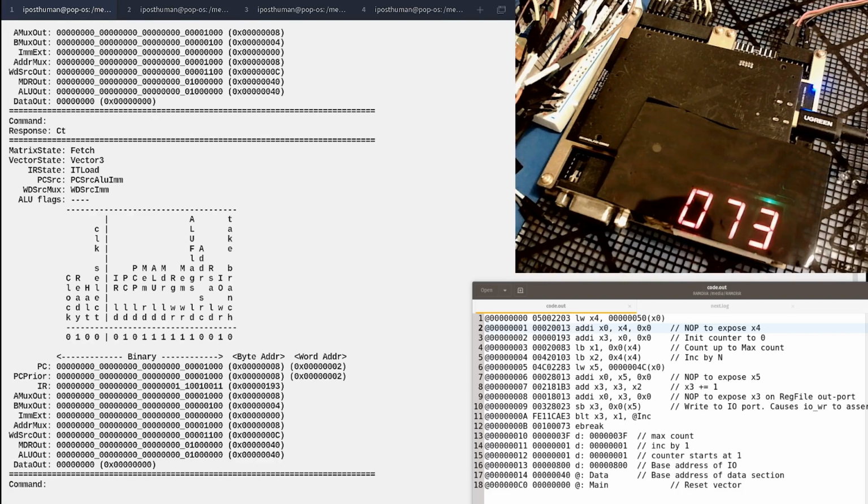There we are. We're now on the next instruction. This is a real instruction that we're actually adding to it. This particular one clears out the register. So we'll continue going through. It's fetching the next instruction. There it is, 2083. So we're going right along. We're going to load X1 with it. We're going to continue. We're going to go to the next instruction. There it is, 4203. Yep, excellent. So this is working. So far, it's working pretty good.